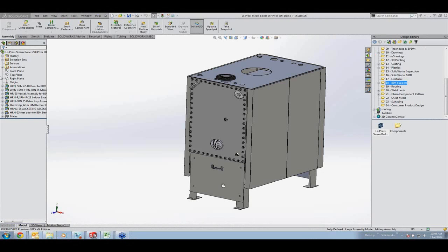Now it's asking for a reference here. Some of you probably know that SolidWorks is very good at telling you what it wants. It's asking for a path link here, a linear edge or reference axis. So I'm going to select the edge here on the circle, and it wants an alignment plane so that this link doesn't just rotate in and out of the pattern here. So I'm going to show planes here and select the front plane here, and then go ahead and turn planes off. It's a nice preview there.